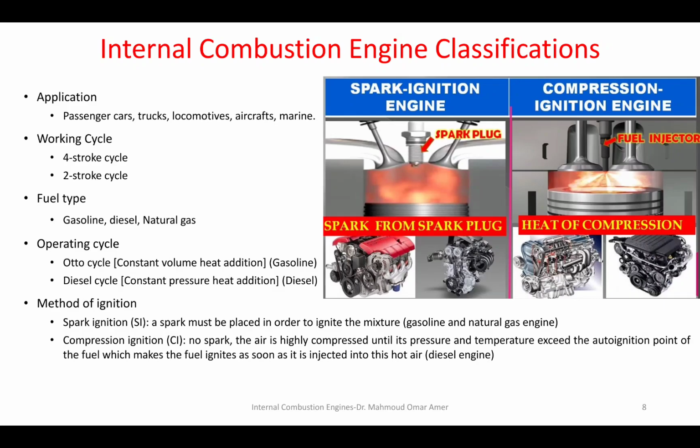From here we will start to differentiate between gasoline and diesel engines. Okay? Starting from the operating cycle. Operating cycle for the gasoline, it's a constant volume heat addition and it's governed by the Otto cycle. For the diesel, it's a constant pressure heat addition and it's governed by the diesel cycle.